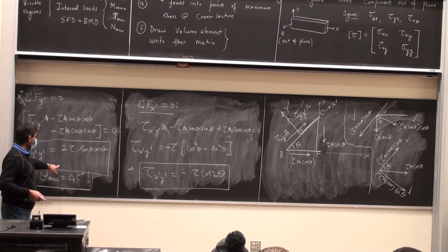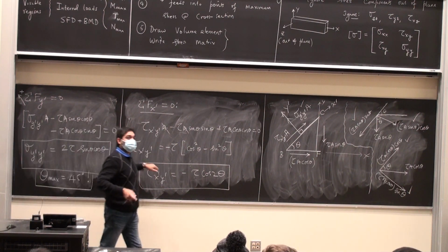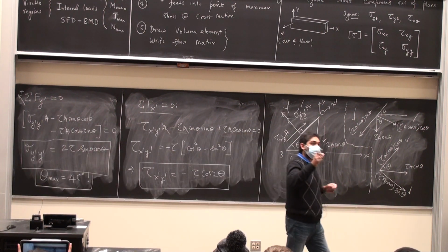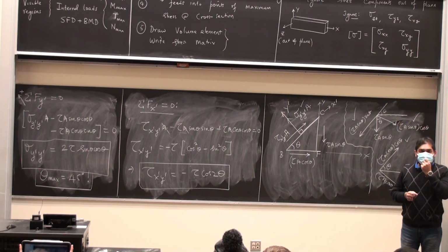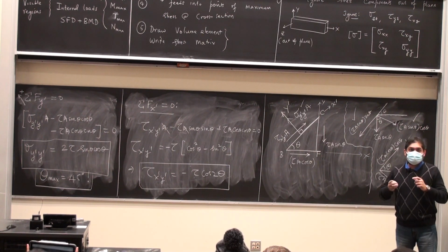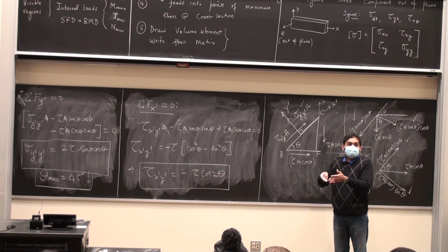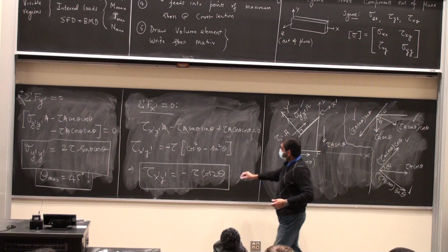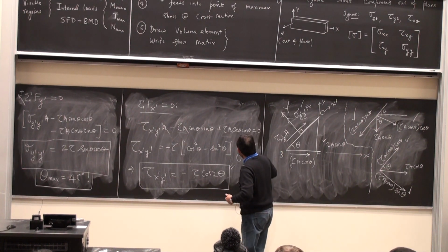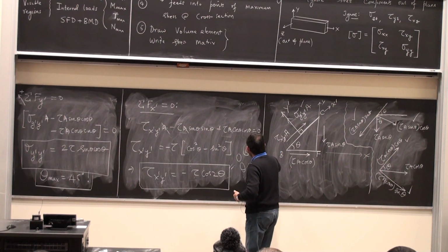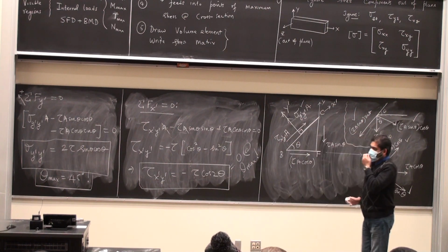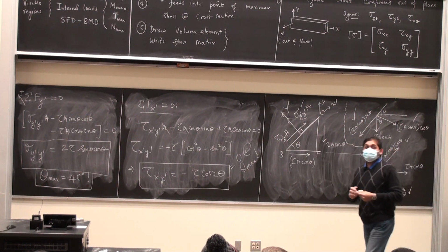So when this stress is the largest, this shear stress vanishes, which is why when you have principal stresses, there are no shear stresses on that plane. This is quite fantastic, in my opinion. Because this is proving to us, from a physical experiment that we are performing right here, that this quantity is equal to 0 at theta max. And it also tells me one more thing.